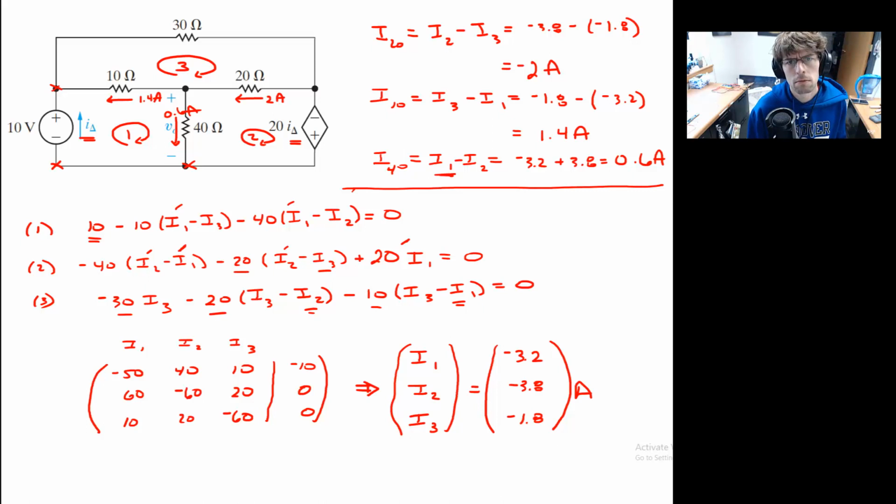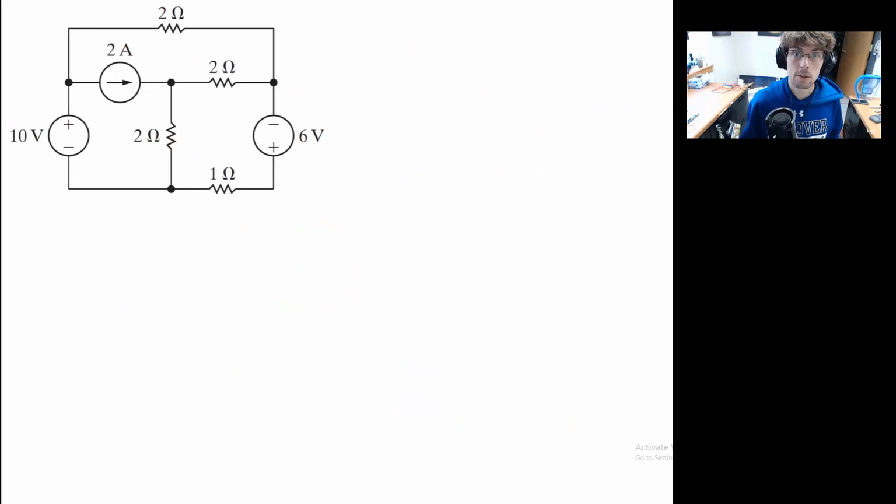At this point, it's just a matter of getting practice with all of it. Let me give you one more. Because there was a special situation in the node voltage method, where if we had two essential nodes separated only by a potential source, we could form something called a supernode.